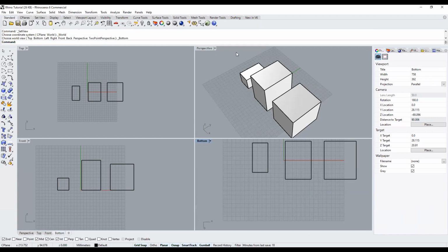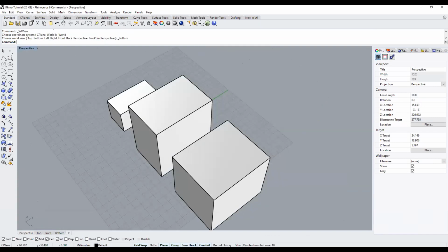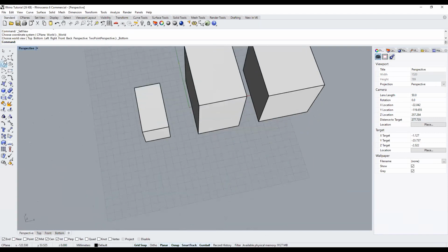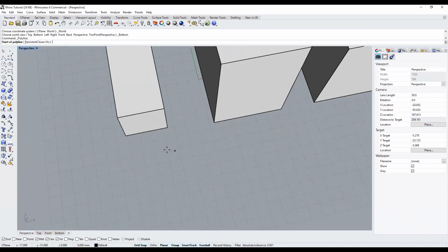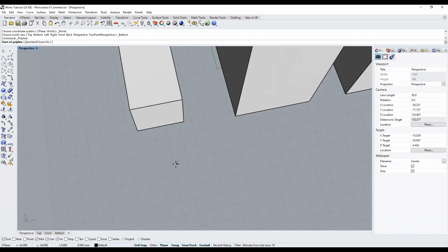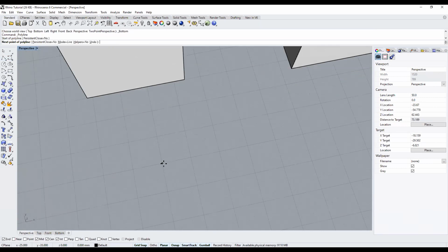And also one of the important tabs on Rhino are these 5 buttons. So you have the grid snap, which lets you say, I'll just draw a line out here. It will snap onto the grid, and this will keep your model as full numbers. So I'm just going to draw a line that is 10 boxes wide.